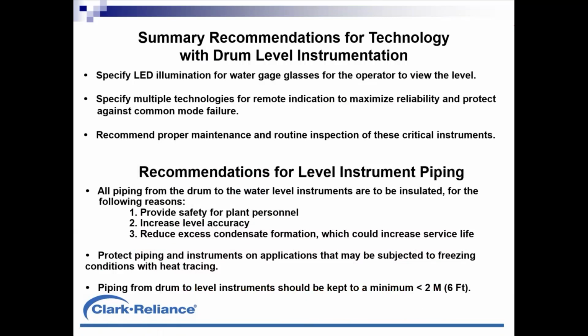So, summary recommendations: consider LED lighting if you're not using it already on your gauge glasses. Consider specifying multiple technologies for your remote level indication applications. Maximize your reliability, minimize your risk against common mode failure. Consider proper maintenance procedures. Consider logging your maintenance on these devices, how often you're servicing them.